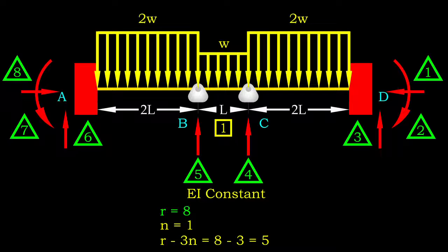When the degree of indeterminacy is high, it will be complicated to solve it using the force method. As an alternative to the force method, we may use slope-deflection equations to solve for the internal moments. Then, we proceed with determining the support reactions using those moments.